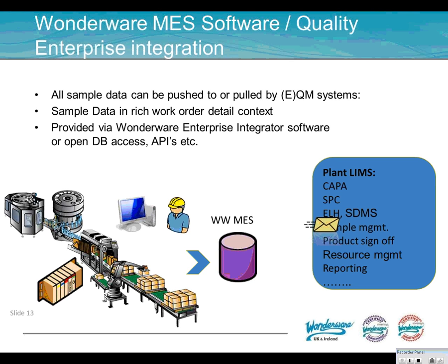And the data transfer can be via the Wonderware Enterprise Integrator software, or indeed just through shared database tables, or even using application programming interfaces such as iDocs and BAPIs in the SAP world, or indeed there is an application program interface library provided for the MES software itself for extracting data from the database.